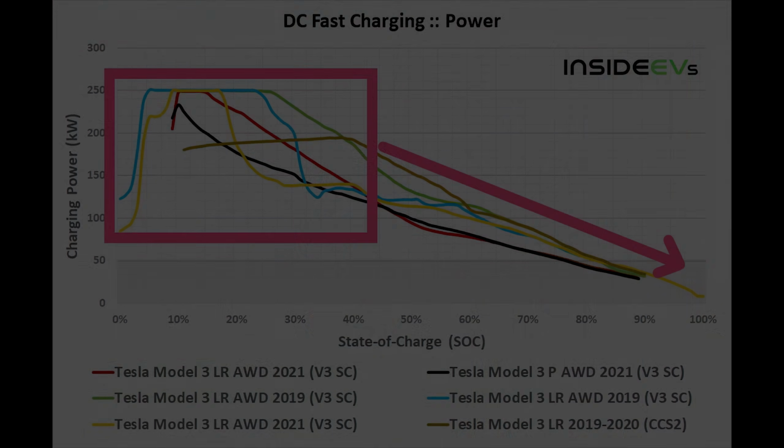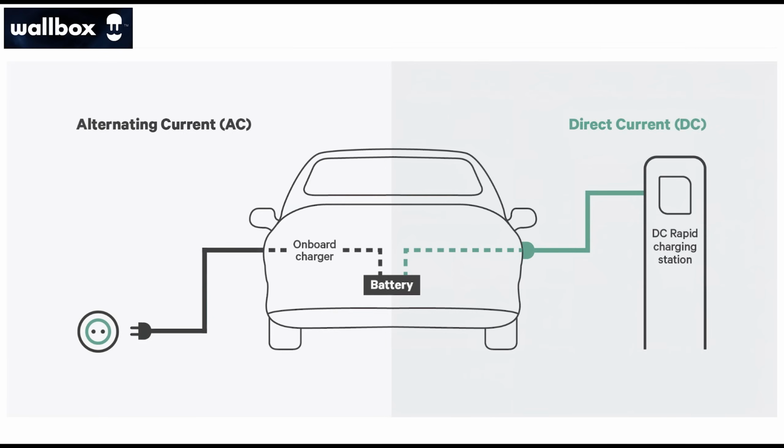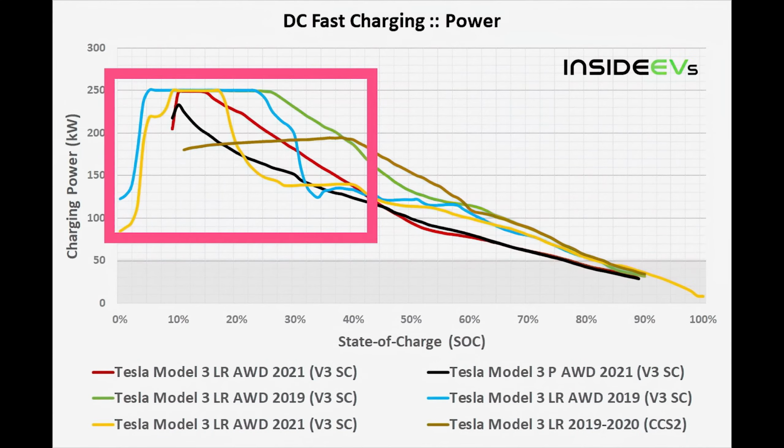Now, that very, very high power might then be limited by the power of the AC to DC converter. So you can think of there being a region where we're not really limited by the batteries for the first 20, 30% SOC from zero. We're just limited by the power converter. And then after that, we start to ride along this constraint dictated by lithium plating. Does that make sense? This is kind of a complicated answer.